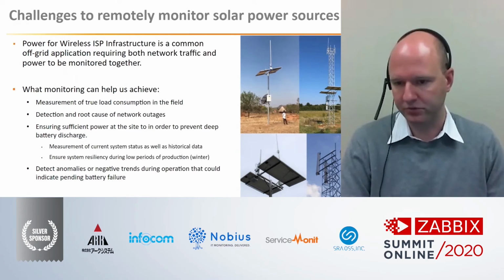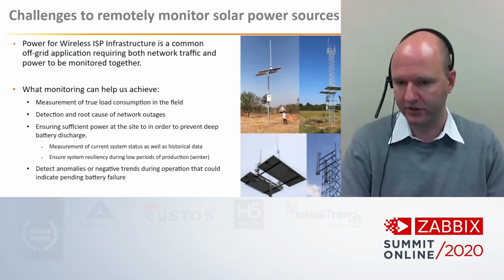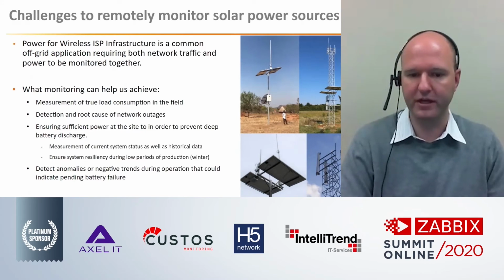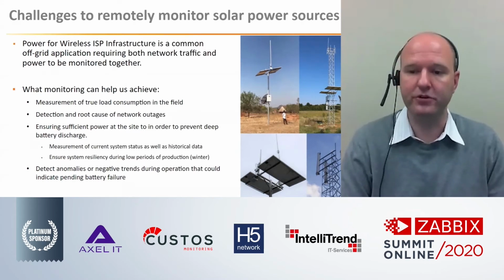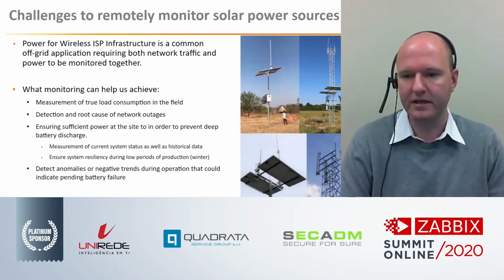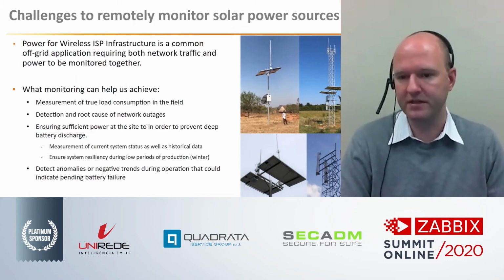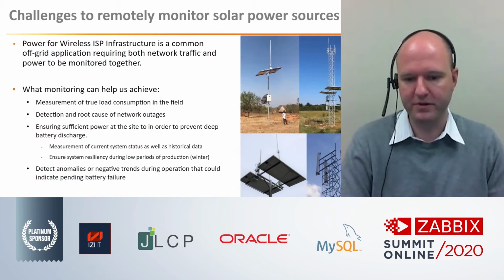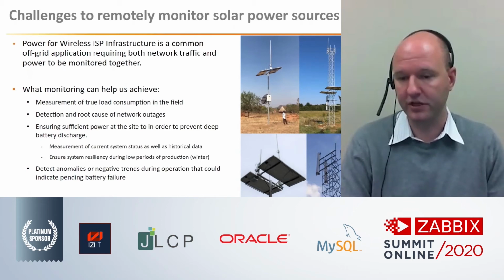So ensuring power at the site also ensures that you have adequate PV to cycle the battery properly, so that when it is depleted of energy each day from powering the loads, it is fully recharged the next day when PV power is available again. And this balance is difficult to manage because you have to always ensure power for the battery, protect the loads, but you may or may not have adequate sun each day. So a number of days of reserve power is often provided in the system to ensure that the site will remain up.